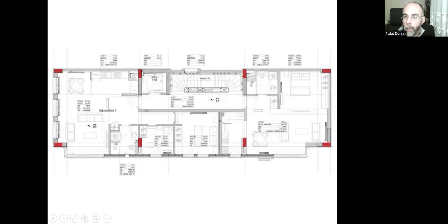But if there is an imbalance, such as shear walls around the elevator instead of placing a column in order to carry the elevator, or shear walls around the staircase in order to carry the staircase, we create an unnecessary imbalance in the whole structural system of the building.